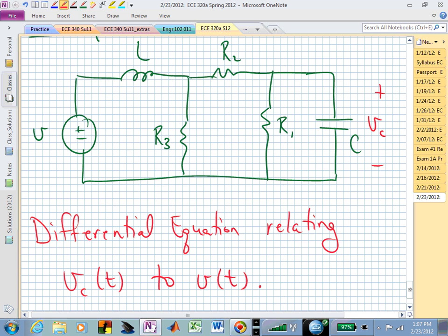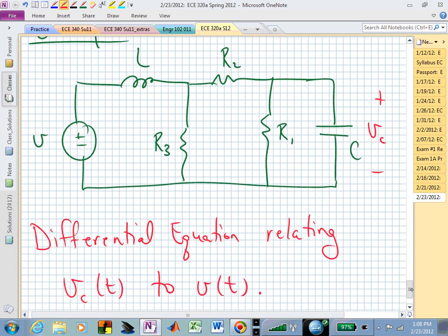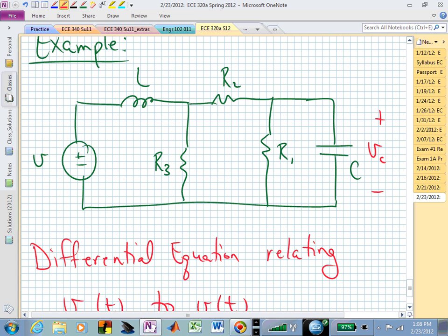Here's the ladder technique. What I'm going to do is start interrelating a lot of these quantities. I can now relate that current, I sub C, with that voltage, V sub C. And I might want to know what this current is, so I'll call that I sub R1.